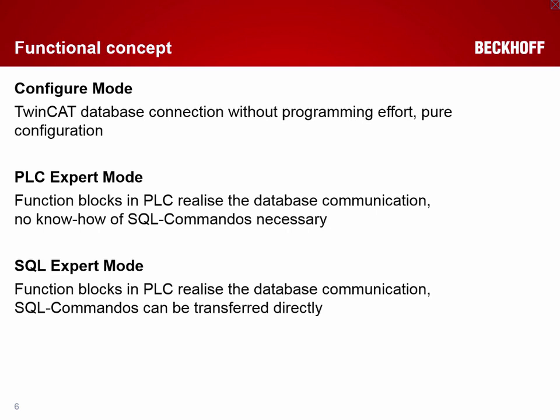Then we have the PLC expert mode, where we have different function blocks for the PLC, and these function blocks realize the database communication, in this case without any necessary knowledge about SQL commands. And then we have the SQL expert mode. Here we can generate the SQL commands directly in the PLC program and transfer them by our database server to the database. So that is a high performance way of communication.